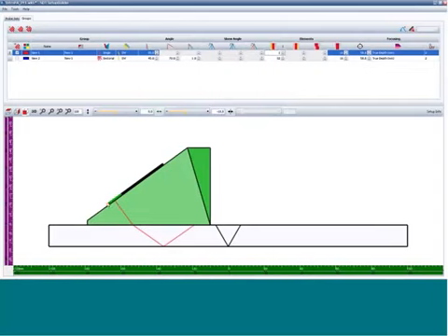Here is probe element 1, probe element 16, and we have a 55-degree refracted angle being generated into the material. Obviously, if I start the element at a higher position, it's in a better position for the inspection. This is a static single focal law,